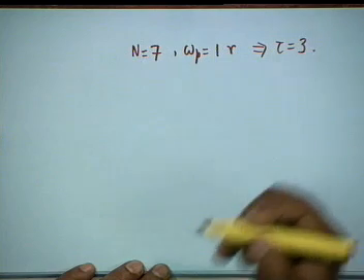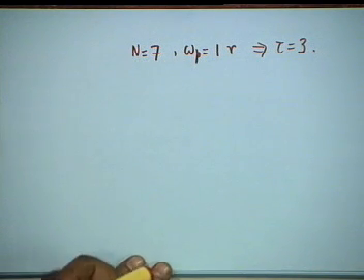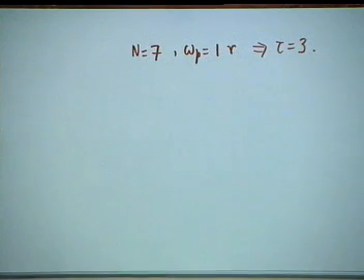In order to obtain the frequency response curves, well, we require the expression for what kind of filter? This is a linear phase filter of which type? Type 1, symmetrical impulse response and length is odd, type 1.